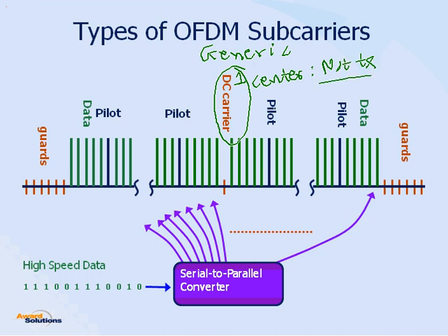There is no energy, no power at all. So if you are a UE looking for 700 megahertz, the carrier frequency at RF, wherever you find minimum energy, that is the center of your system, exactly 700 megahertz. That would be the carrier frequency.